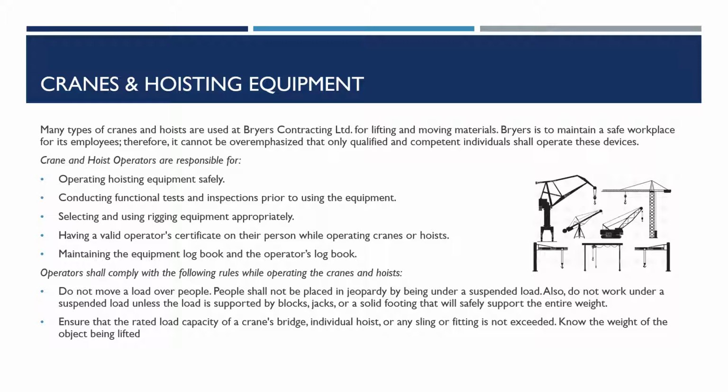Crane and hoist operators are responsible for operating hoisting equipment safely, conducting functional tests and inspections prior to using the equipment, selecting and using rigging equipment appropriately, having a valid operator certificate on their person while operating cranes or hoists, maintaining the equipment logbook and the operator's logbook.